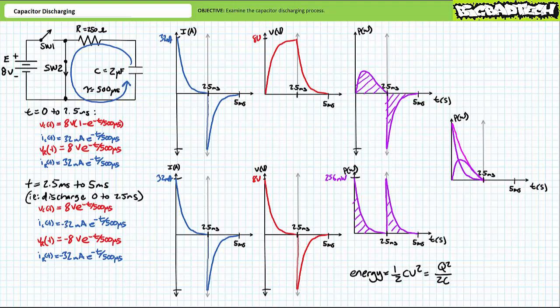The math details are admittedly a little heavy, especially if you spent a couple years chained to a desk learning calculus. However, for our purposes, you only need to really concern yourself with the basics. During the charge phase, the resistor experiences time-variant positive voltage, positive current, and thus dissipates time-variant positive power. During the charge phase, the capacitor also experiences time-variant positive voltage, positive current, and thus dissipates time-variant positive power.